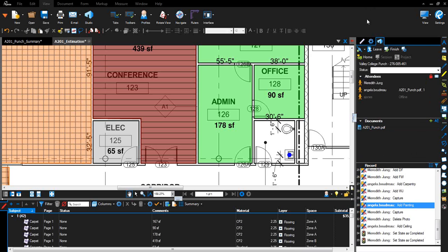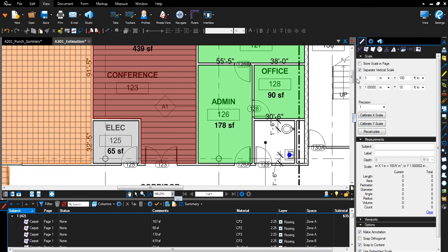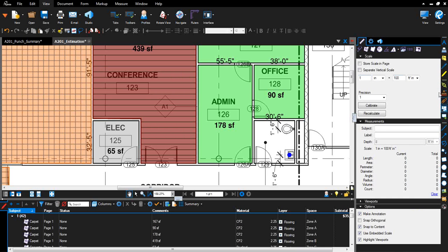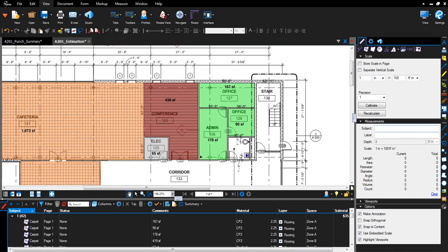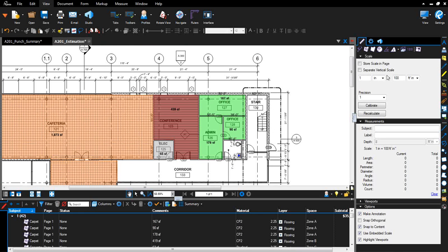Okay, now we also had a question about measurement settings in terms of how we go ahead and set and calibrate and recalculate all of these things. Calibrating when you have a known measurement on the page is the easiest way to go through and set those scales. But these scales can all be set manually. Typically the left-hand side is either shown in inches, centimeters, or millimeters, and the right side is either shown in inches, feet with inches, or inches, and that's just a drop down there.